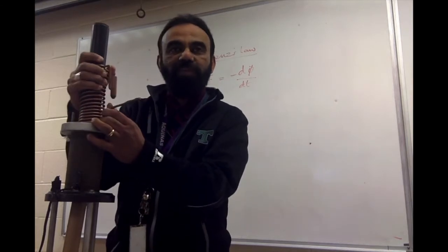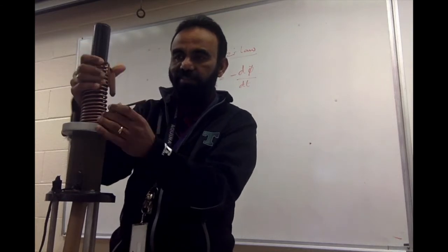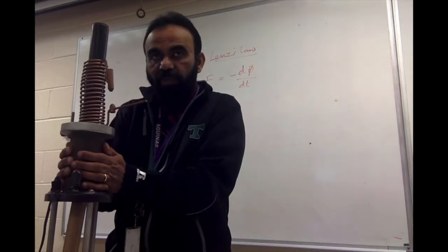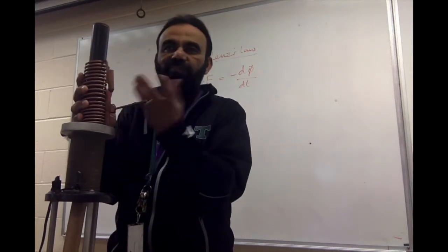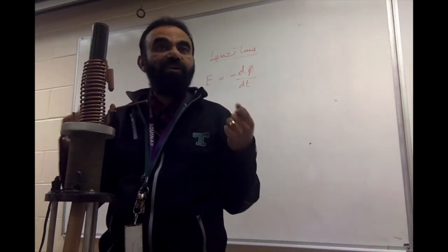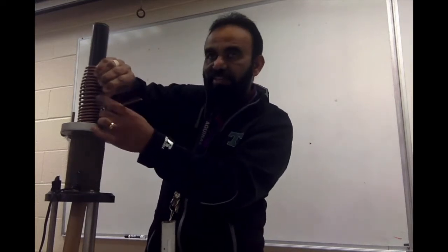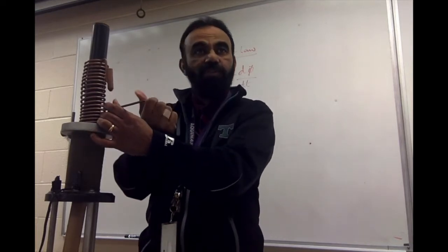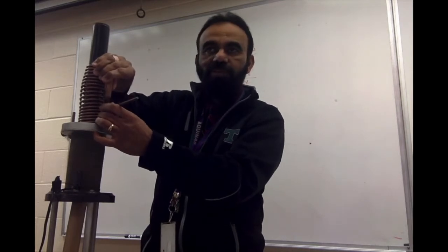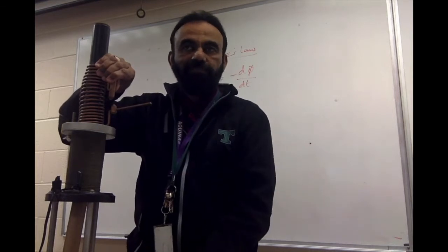Yeah, so what is happening over here? There was a strong current here. That's why you can see it's all eaten up. The copper is all gone. When I was touching here, there was an EMF induced. The 110 volts over here is creating a voltage of roughly 2-3 volts over here, which is safe for me to touch. So 2 or 3 volts is not going to do anything to me. So I'm not getting any shock by touching this. But when I touch here, this entire coil becomes low resistance, and so the current will be pretty high, and so you saw the sparks jumping across, and the heating effect is so high down here that it is melting the copper. All right?